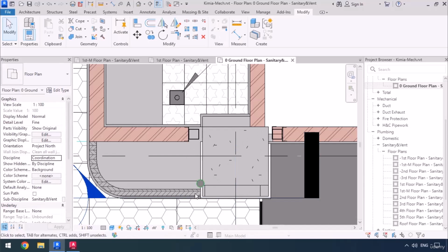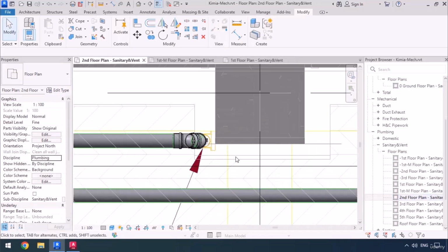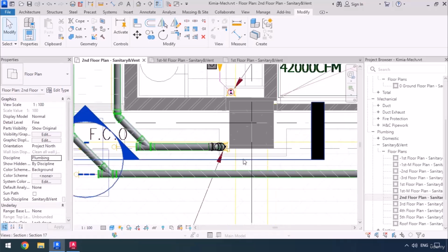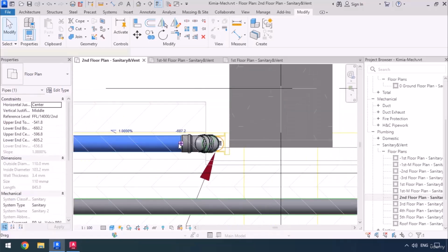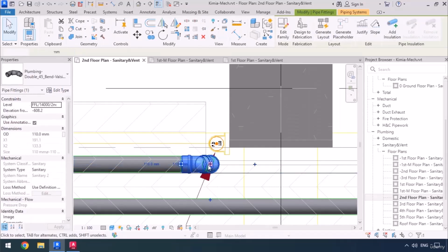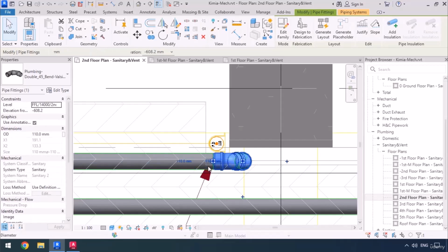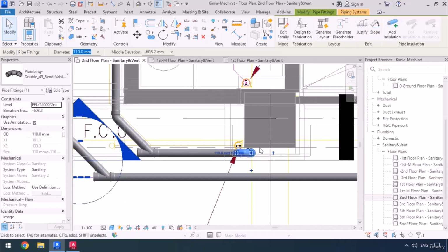Now we're going to need to change the pipe's direction from this point and lead it straight down. Or we could move to the upper level where we again had that problem and maybe expand the column's cover at this point, just in case that repositioning of this pipe might mess up with the slopes or the fittings. So in other words, we could also make the column cover this pipe as well. So first I'm going to bring this lower, and then I'm going to extend it in this direction. So overall, we're making the riser go from here.